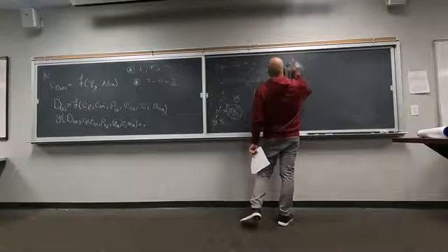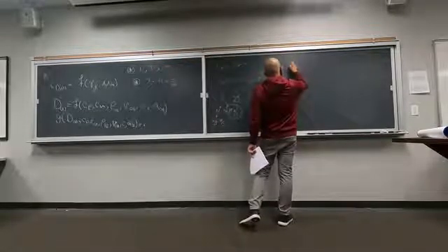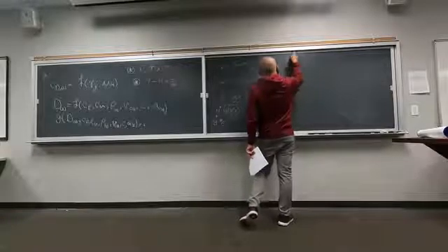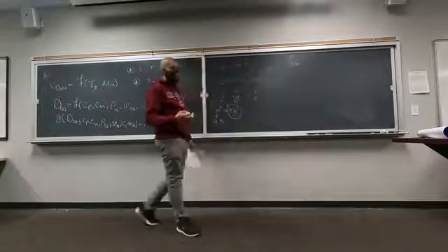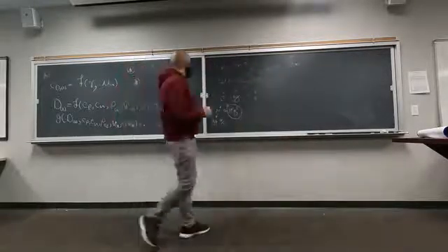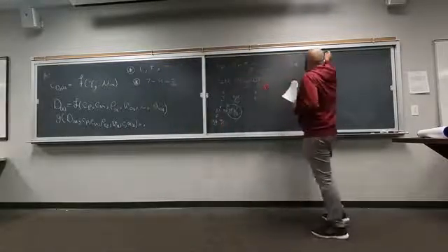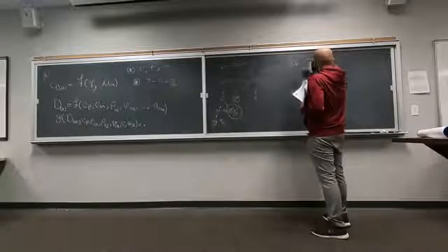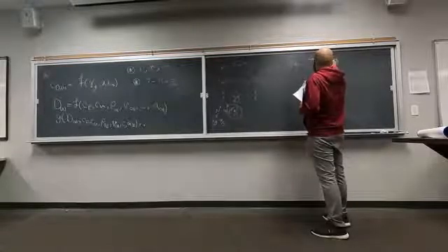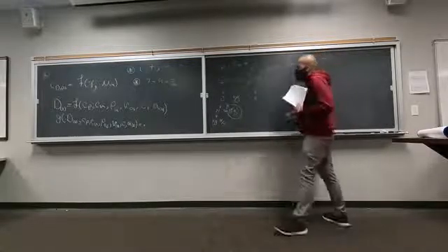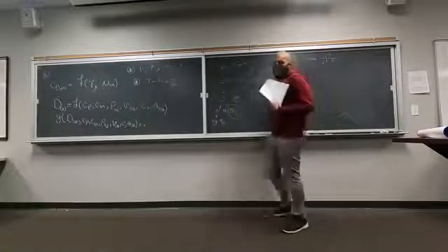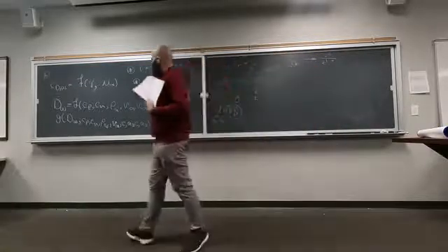I'm sorry, so this is meters squared per second squared Kelvin. So this is going to be your dimension for Cp and Cv, which in this nomenclature is length scale to the power 2, time to the power -2, multiplied by degrees. So dimensions for Cp and Cv.